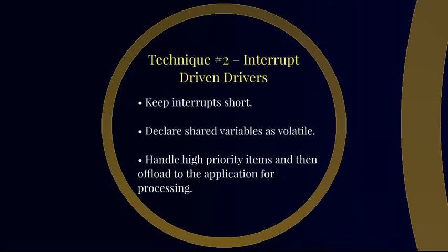Technique 2: interrupt driven drivers. Using interrupts in a driver is fantastic because it can dramatically improve the execution efficiency. Instead of checking constantly for whether it is time to do something, an interrupt tells the processor that the driver is now ready and we jump to handle the interrupt.